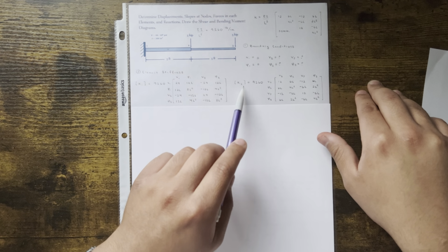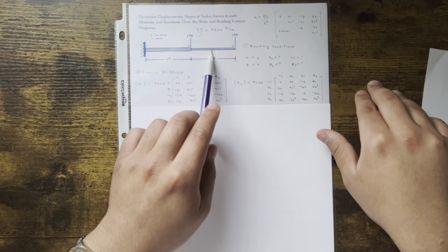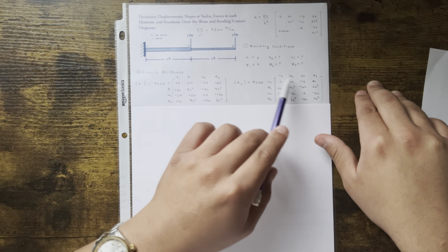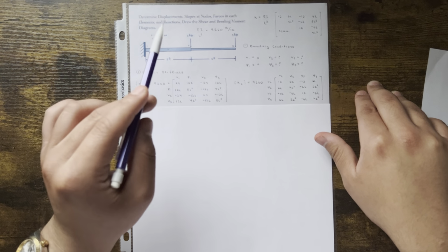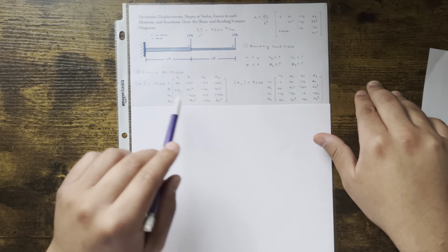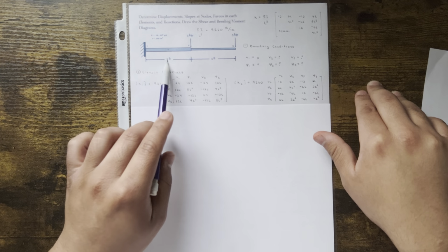Then for K2, same thing, right? 9260, that's just the true value of the stiffness. It's V2, Phi2, V3, Phi3 because it's between nodes 2 and 3, okay? So once you have all, and again, we know L, by the way, that's just length, 60 inches. So all these values we know. We know this number, so that means we know K for every element.